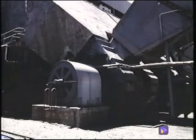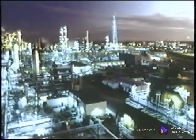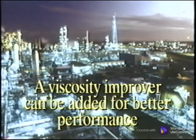oil. Light loads require a light oil, and if a heavy oil is used, extra energy is required to move the components, producing heat and degrading the oil. High temperature applications require higher viscosity or heavier oils than colder operating temperatures. Viscosity must be adequate to separate the moving parts at the operating temperature of the machine. When a machine must operate in both cold and warm temperatures, such as outdoor applications, an additive package called a viscosity improver can be added to the oil to make it perform suitably in both environments.